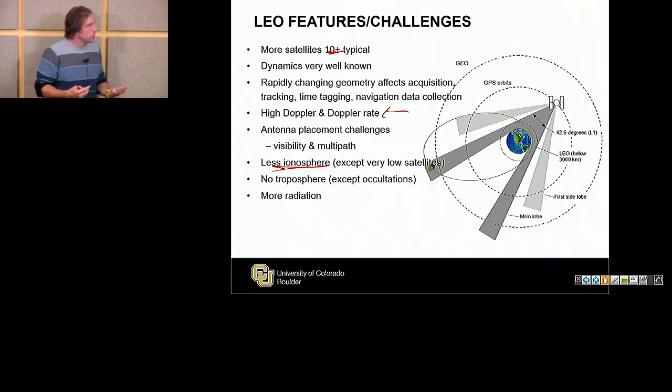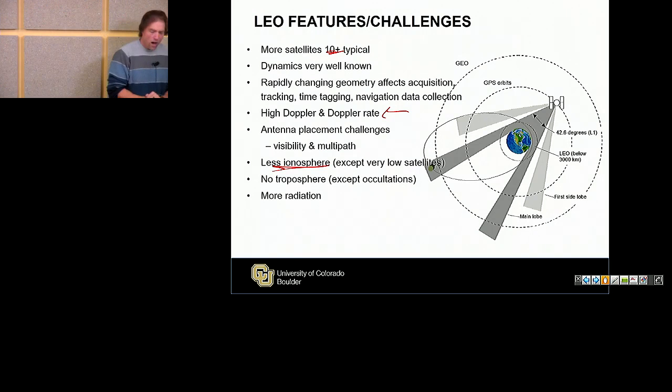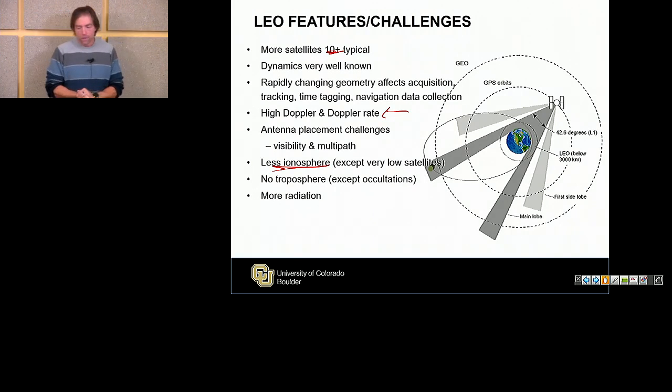So if I'm trying to do GPS in LEO, this is really what happens. If you are designing CubeSats, you can go to any of a couple of different major vendors. Novatel, for example, is one. Their receivers are a few thousand dollars. If I buy it off the shelf, it won't work in space because of this altitude and velocity restriction. If I can prove to them that I'm a suitable user, they will give you new firmware you can download on that receiver, which will remove that altitude and velocity restriction, as well as open up the Doppler search space so you can use it.